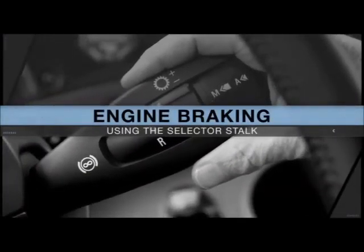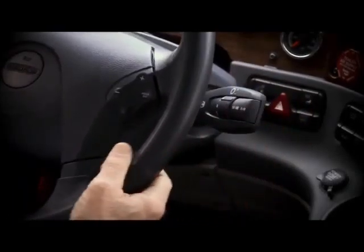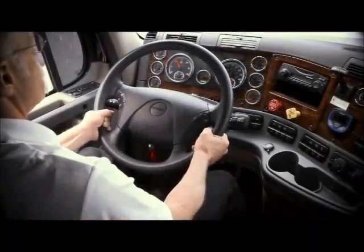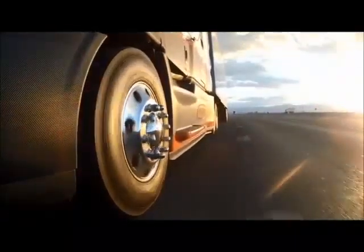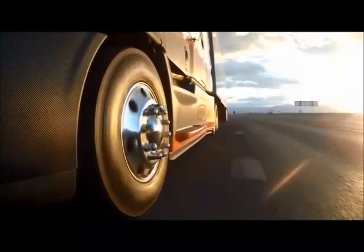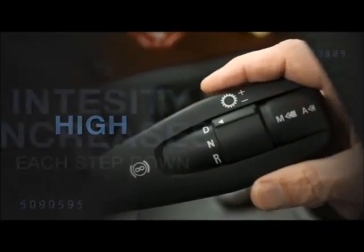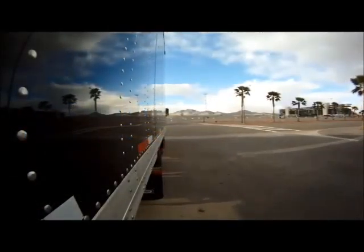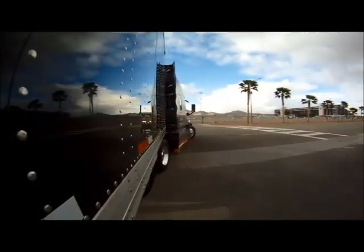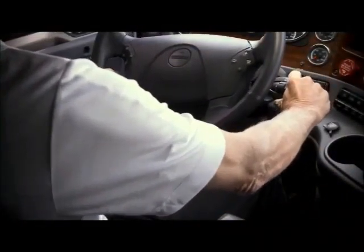Engine braking with the DT12 can be set by rotating the shifter stalk clockwise. The top position is the off or auto position, which will be explained shortly. At the three lower positions, the engine brake is on and the intensity, low, medium, or high, increases with each step down. Engine brakes will work like any other compression braking. Once you let off the throttle, engine braking power will activate, if set to low, medium, or high.